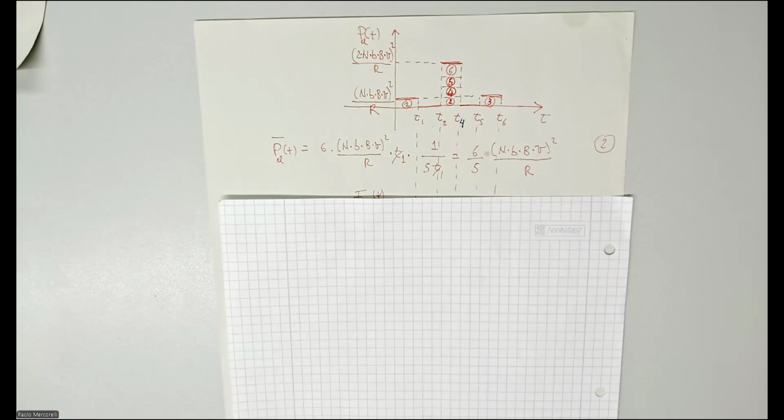Because the problem of designing the actuator to work is the temperature. The temperature should be maintained lower and lower, because it's the temperature which damages the actuator. High temperature, this means high power, damages the actuator. Therefore, very often we give the possibility to relax the motor with this part between the magnetic elements with zero, in order to reduce somehow the power.